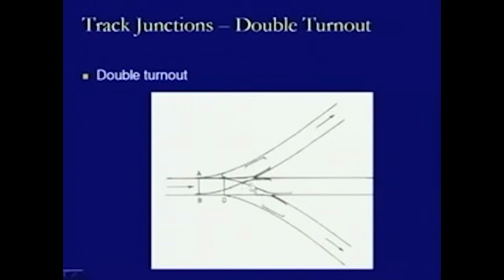So, this is a V, and at this V again there will be a pair of wing rails provided like this. So, this is another place where the crossing will be provided. So, we have three crossings, and depending on the flexure, this crossing may be in the central position, or it may shift towards either the left or towards the right.